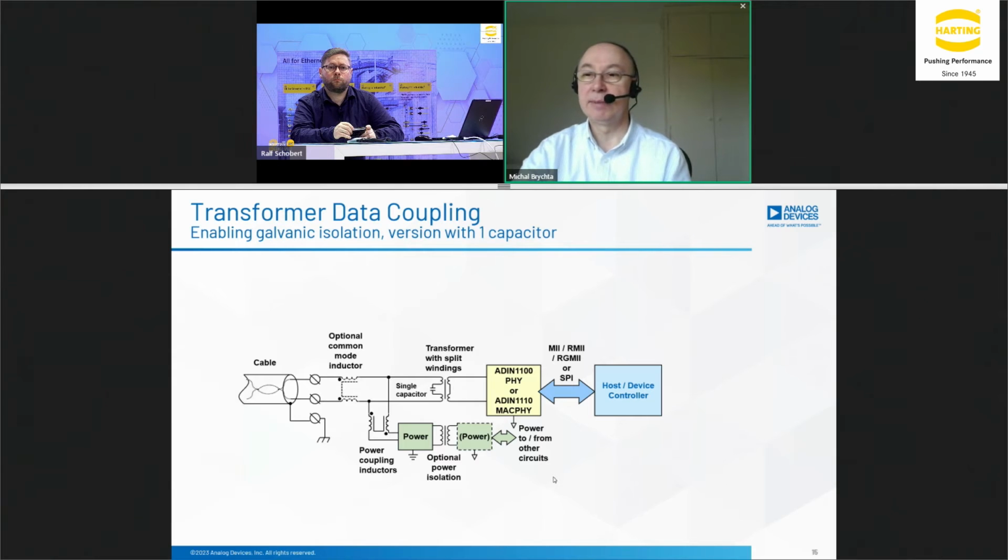And again, I'm covering this topic because that's one of the questions that I'm quite often being asked, how to couple the data and power. Now, if we look at the power, there's quite a lot of inductors. So there is a transformer, there is an optional common mode choke, but mainly we will look at the power coupling inductor because that's the inductor that is carrying the whole power.